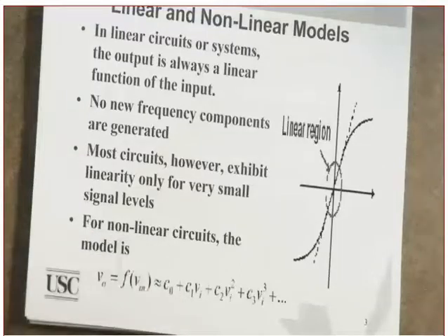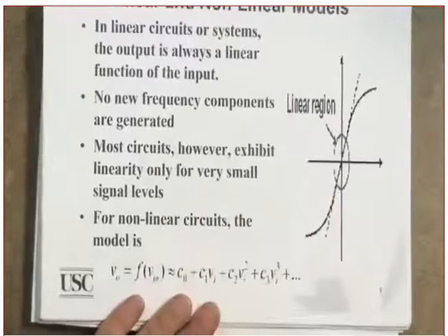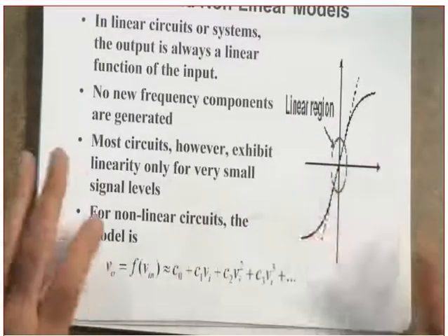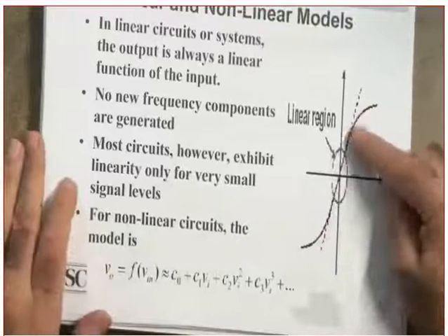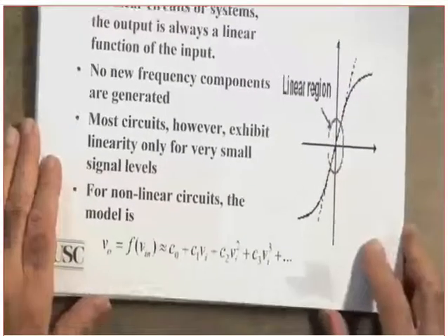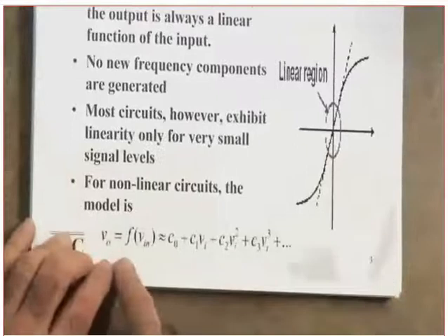They are bandwidth efficient, but they are power inefficient, because you are operating the amplifier below the maximum, or backed off. You backed off from the maximum to that region. Clear? Let's see how we model it.